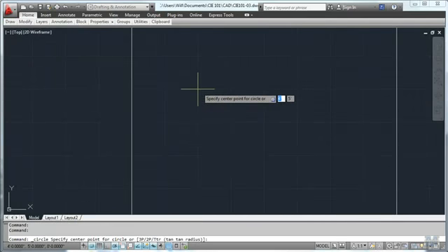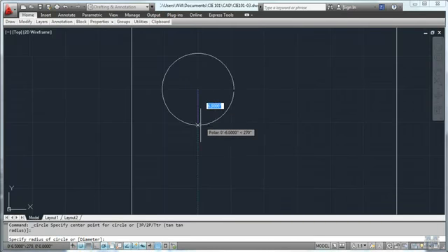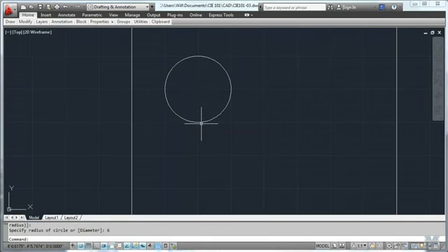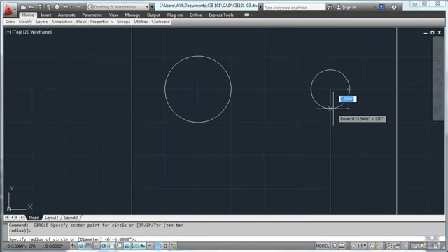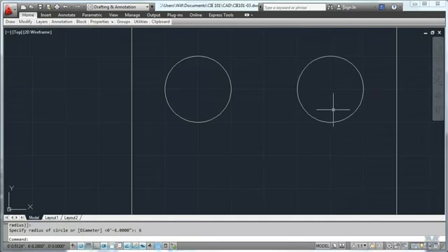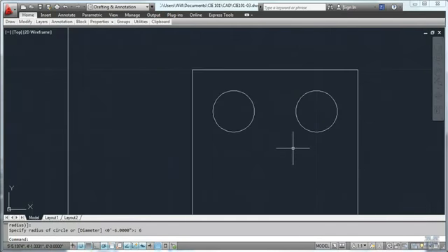And I think I can zoom in far, get the grid to work for me so it'll snap. You can see the cursor kind of bounces around in those 1/2 inch things. So let's type in 6. I don't have to hit inches because inches is its normal way of working. And there's one circle. You'd have to hit the circle again, or I can hit the space bar and it'll make another circle. The space bar just repeats whatever command we just put in. So there's some circles for eyes.